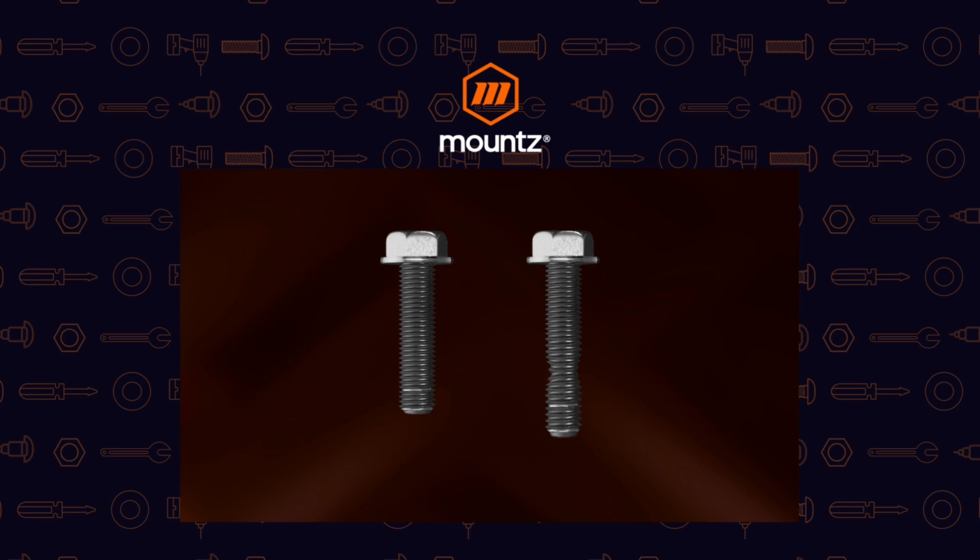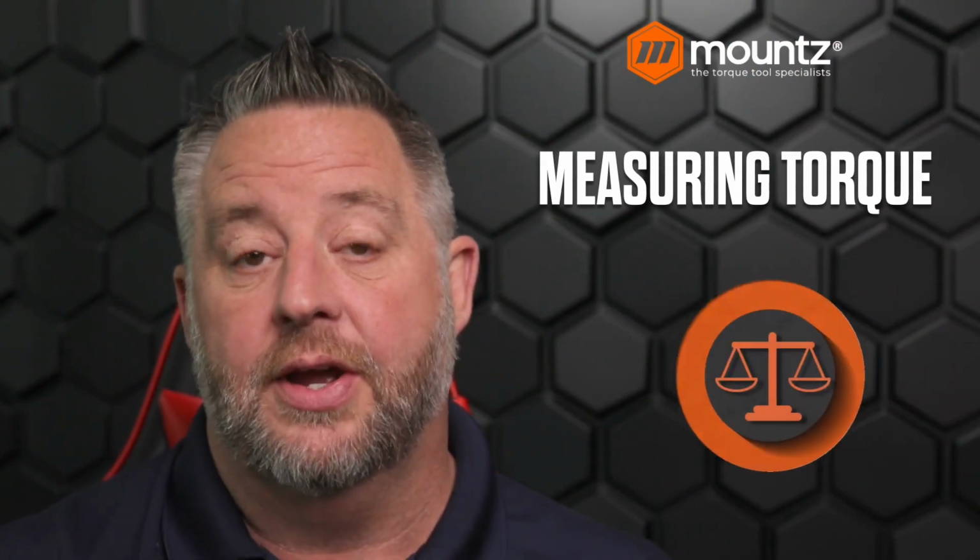You'll see here that the fastener on the right has reached its yield point. If a fastener has been stretched past its yield point, it will no longer return to its original shape, as we see on the fastener on the left. So this is the idea of what we're trying to achieve with the actual bolted joint fastener.